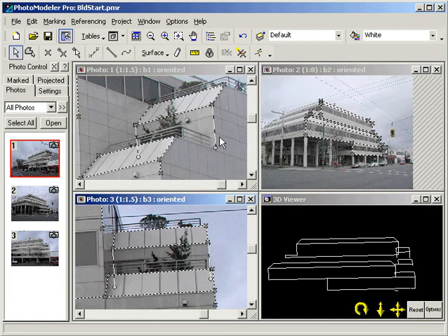In photo 1, the photo angle is rotated to the right, and we have a rotated view of the edge. If we were marking a horizontal edge, then we would have to get photographs from different heights. These requirements also apply when doing cylinders, which we will look at in the next segment. If we select the edge, the angle between the photos is shown in the status bar. We have an angle of 33 degrees.